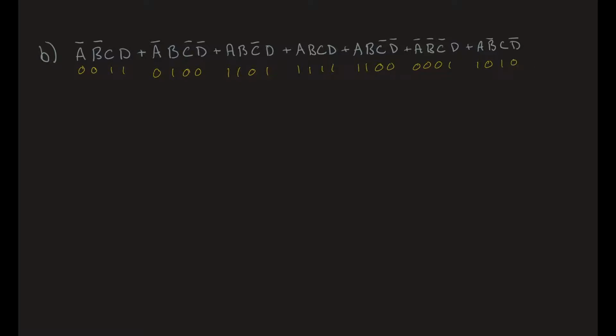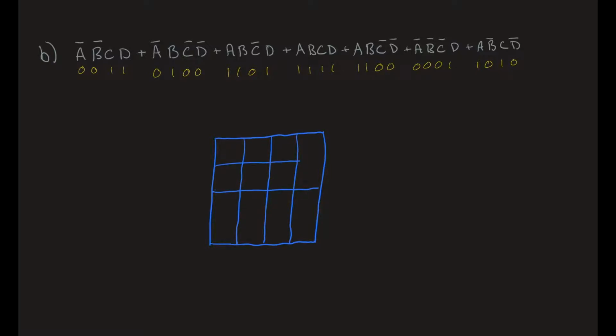Alright, what's our K-map look like? It is a big square. It has 16 cells. We'll draw it out. Big square, cut it in half both ways 3 times. That's one way. That's the other way. In a little bit, I drew one out, and I just copied and pasted it and made it nicer, so you won't have to look at my blue drawings forever. AB, CD, 0, 0, 0, 1. What comes next? Yep, 1, 1, 1, 0.